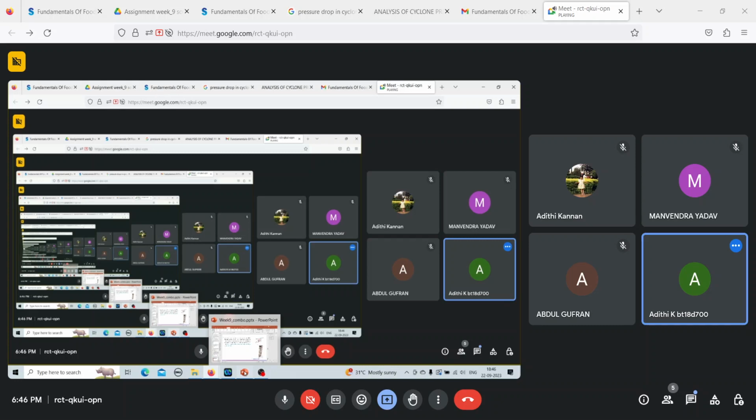The entire basket centrifuge is a cylinder, and you have a hollow cylinder right now, where the center has nothing and the annular region has your liquid because of the centrifugal force. So the volume can be given as pi into R square minus Ri square into h.